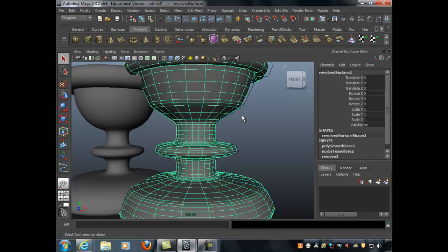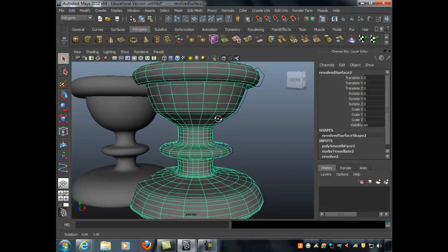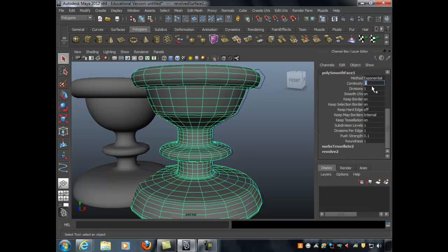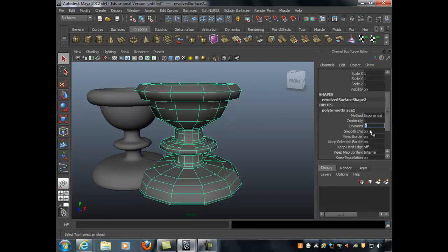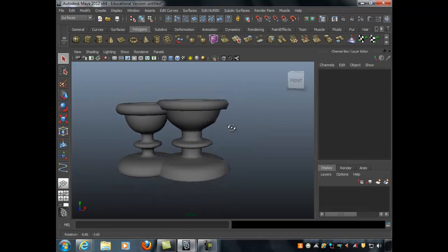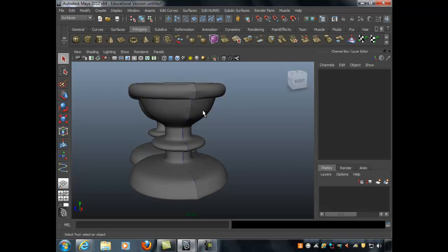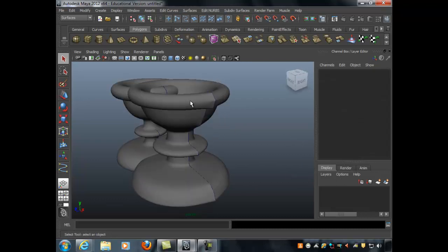The reason why I was popping back and forth here is Maya's giving me this extra edge in here when I revolve the mesh. I shouldn't be doing that. So now we have an asset that can be a game asset by changing the divisions to 0, or a film asset by changing the degree to 3, and you have one asset that serves all purposes. You'll notice here that I have this little spike here at the side. Can anyone tell me why that's occurring?